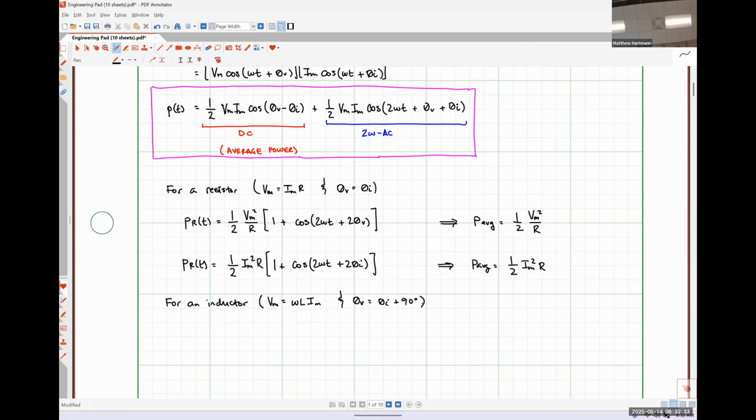It wouldn't be exactly 90 degrees for a couple of reasons. One, the resolution on these oscilloscopes is not great. But the other reason is that the inductors that we used are not pure inductors, because it's impossible to generate a pure inductance that has no resistance whatsoever, because we know that real wire has some amount of resistance, right? So we should have got a number pretty close to 90 degrees, but it wouldn't have been exactly 90. Here we're talking about pure ideal inductance, okay?